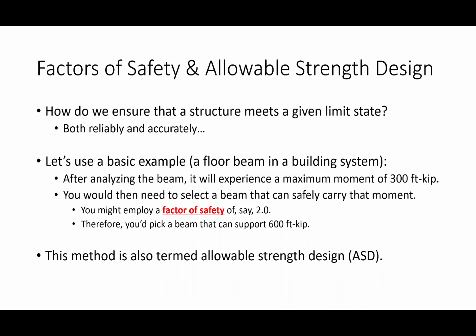The name for that design philosophy in steel design is allowable strength design, or ASD. Sometimes you might call it allowable stress design. Allowable stress design, allowable strength design, same thing. So whenever you hear allowable stress or allowable strength, I just want you to think factor of safety. That's basically what it is. Sound good?